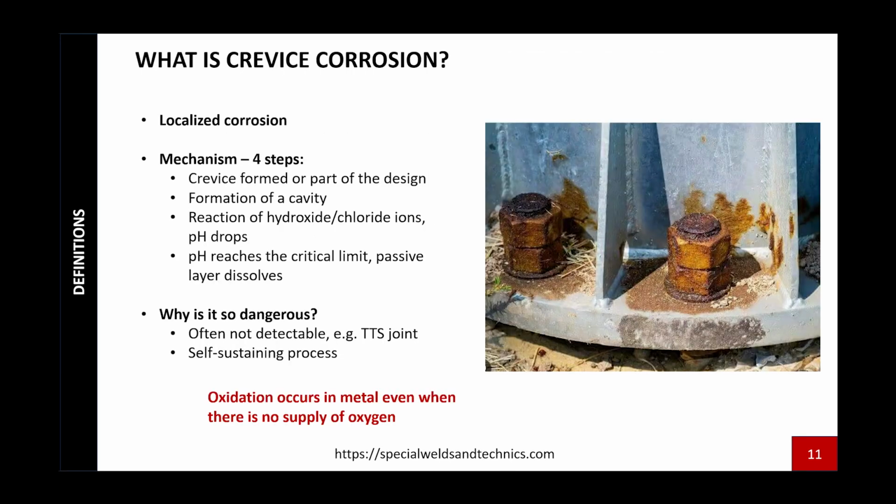And finally, let's take a closer look at crevice corrosion. This is also a localized corrosion, and it is very similar to pitting corrosion. The only difference here is that we need at least 2 neighboring bodies, and of course between them a confined space. Even the formation mechanism is identical to the previously described pitting corrosion.